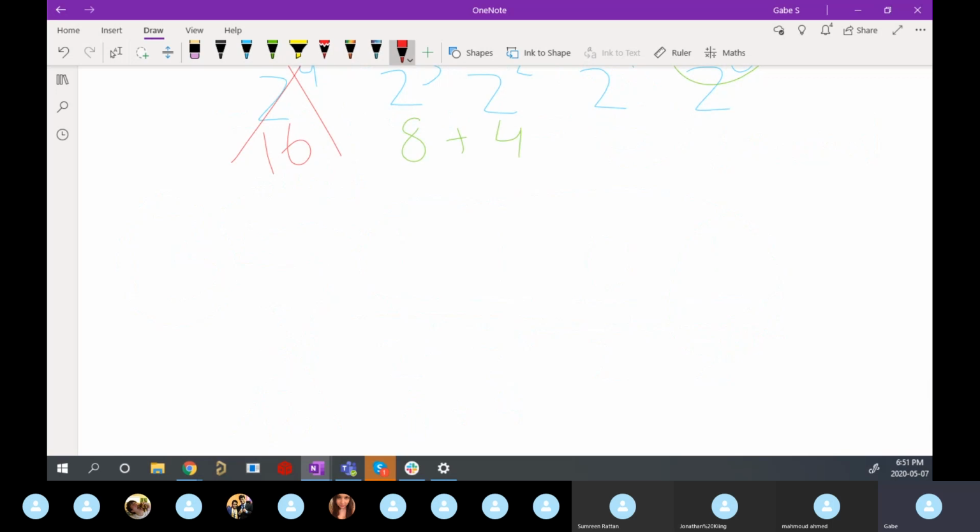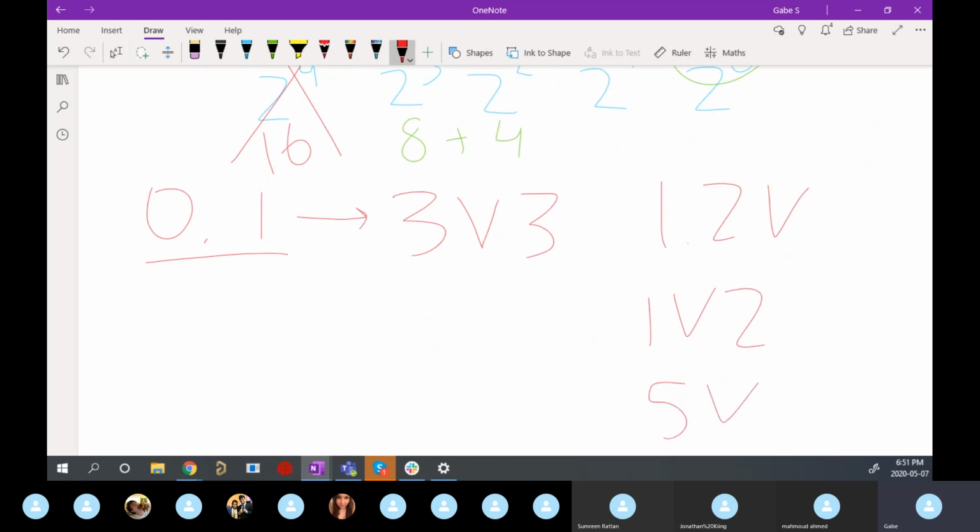So now that we know how a computer works, 1s and 0s, and we know what the logic level means, let's go back to our 3.3 volt logic level. Sometimes you can write 3v3 instead of 3.3 volts. That's common in terms of history because on old schematics, people would write 3.3. You can see this dot really gets lost, right? And sometimes you think of it as a 33 volt or it was misprinted and you can't tell. So 3v3, instead of saying 1.2 volts, people say 1v2. 5 volts is easy. But that's just a common notation that people like to use and that we probably should use from now on. So we know that 0 and 1 with a 3.3 volt logic level would become 0 volts and 3.3 volts, right?